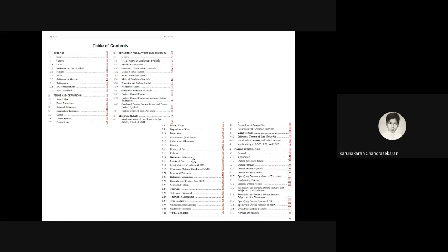and take the basics and go to the lab, do your own measurement and understand the datum features, the maximum metal condition and the minimum metal condition. Draw a simple diagram and mention the datum references with reference to the IPC standard, not the ASME, because ASME will give you more elaborate detail on mechanical components, but we have to restrict ourselves to the printed circuit board alone.